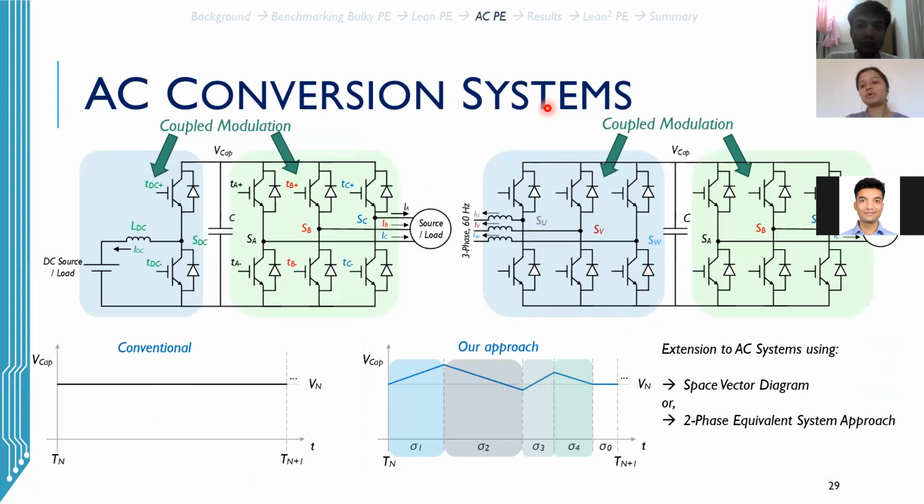So as you rightly pointed out, there's an interesting point to make: we are currently working with 3-phase systems, and this comes with the assumption that if you look at every instant of this three-phase system, the energy requirement is constant. But in the case of a single-phase system, as you pointed out, the energy requirement is not constant.